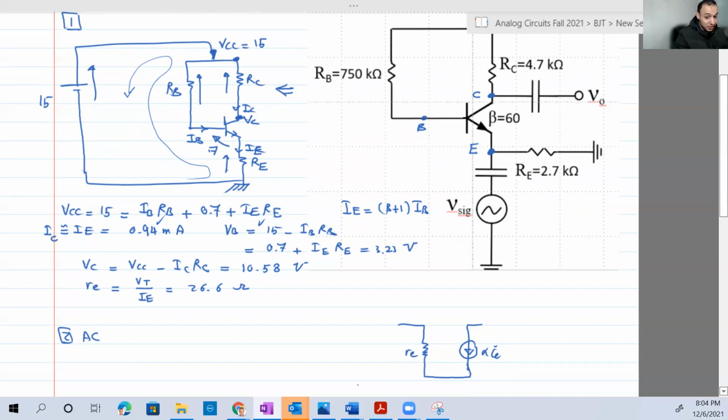Now, a very important thing: what are the nodes? You have here 3 terminals. You have a terminal here, a terminal here, a terminal here. If you confuse that, the rest is wrong. So this is emitter, this is collector, and this is base. That's not enough. Where is IE? You say here alpha IE, this is a dependent current source. So it's dependent on a current, alpha IE, alpha is constant. We need to know where this IE is.